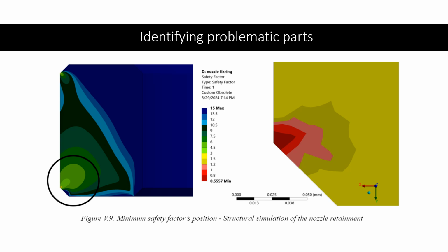So basically, when we did this grid dependence test, as you could see in the slide before, there were some higher von Mises stresses when we refined our mesh even more. And if we refine our mesh to infinity, there can be some problems with that.